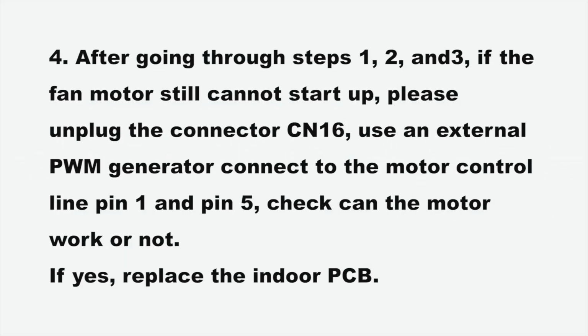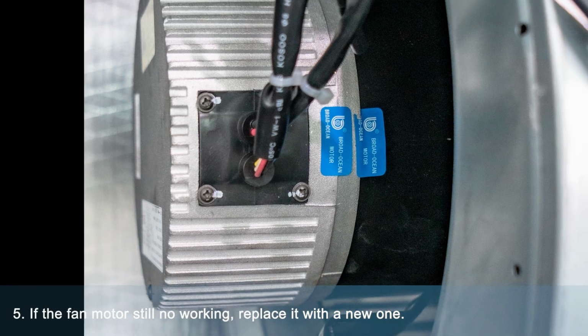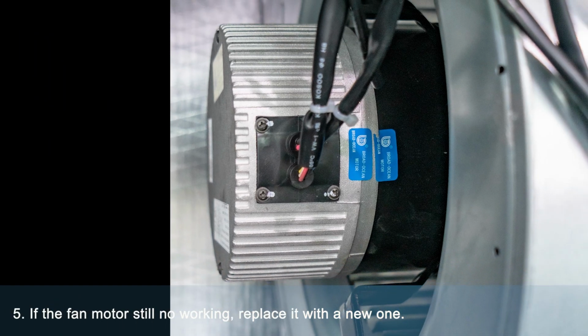4. After going through steps 1, 2 and 3, if the fan motor still cannot start up, please unplug the connector CN16, use an external PWM generator, and connect to the motor control line pin 1 and pin 5 to check whether the motor works or not. If yes, replace the indoor PCB. 5. If the fan motor still does not work, replace it with a new one.